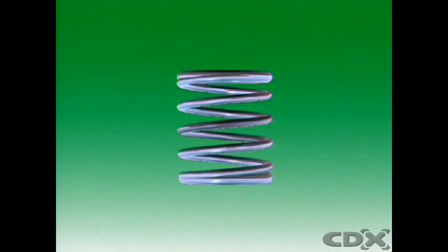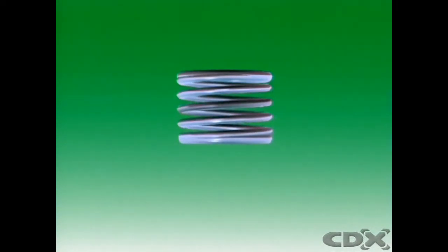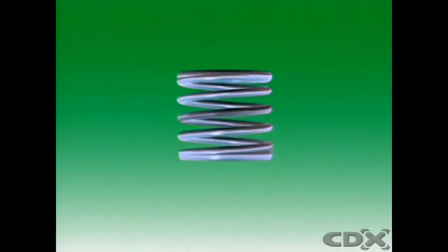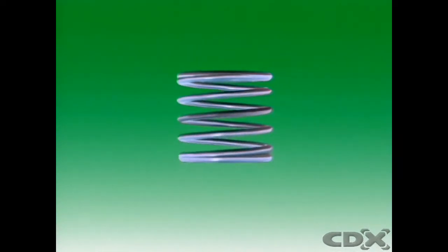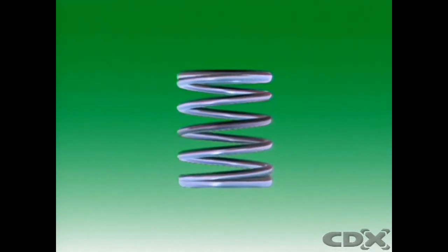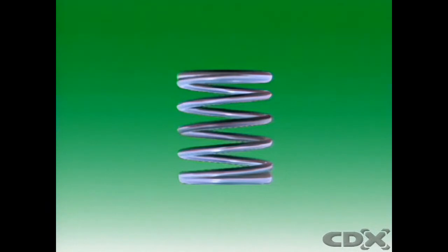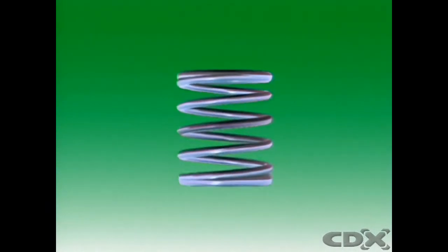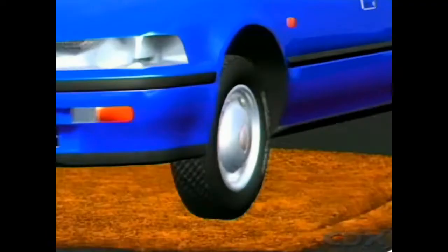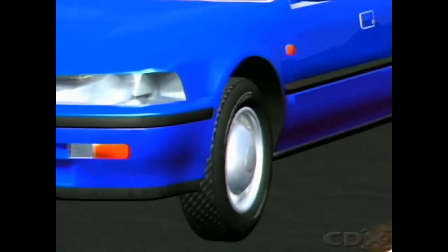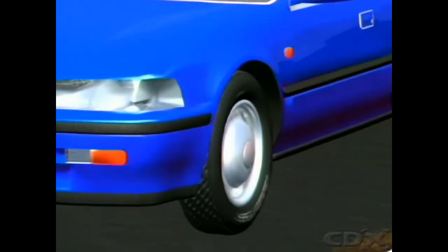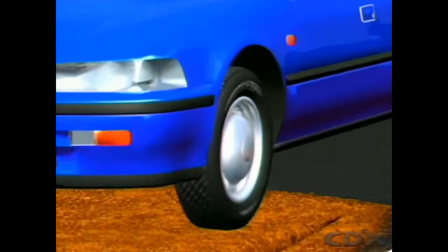When a vehicle strikes an uneven surface, the springs are deformed from their original shape. They return to their original position, but tend to overshoot and set up oscillations. This makes the vehicle bounce up and down, which makes the ride uncomfortable. It can produce forces that make the tires bounce, and a bouncing tire won't grip the road surface well.